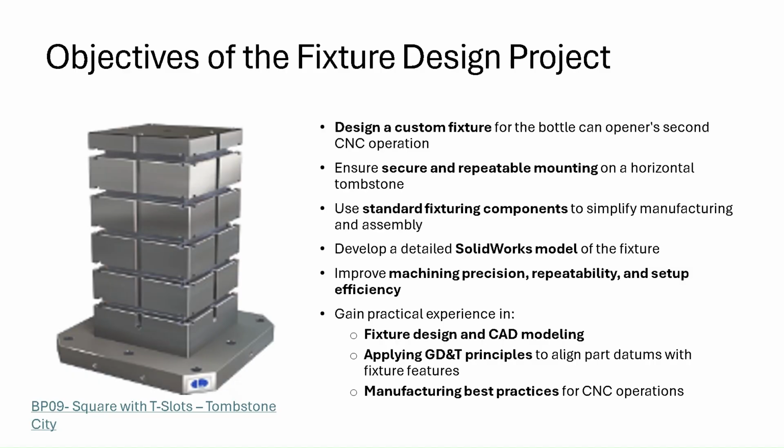Here we have the objectives for the fixture design. First, we design the custom fixture for the second operation. Then we ensure that it's secured and there's repeatable mounting on the horizontal tombstone. Then we use standard fixturing components to simplify manufacturing assembly. Then we create a detailed SolidWorks model. Then we wish to improve machining precision, repeatability, and setup efficiency.